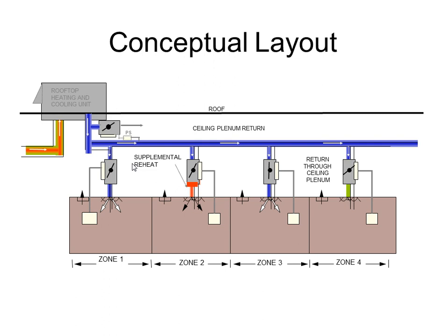Here is a conceptual layout of a VVT system. Pretty simple. You've got a rooftop unit, a bypass damper, it's right here, and then your 4 zones of control. Just going to go into a little bit of how the general sequence and system is supposed to work here. To start off, each of the zones has its own space temperature sensor. That's these little white boxes here, and these zones are talking to the controllers for each of these zone dampers.